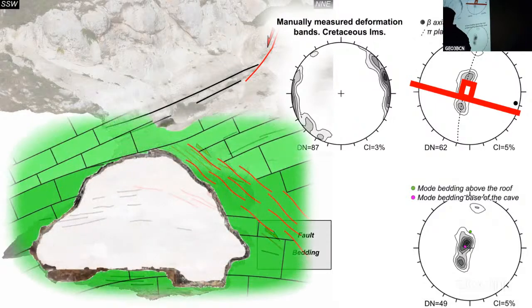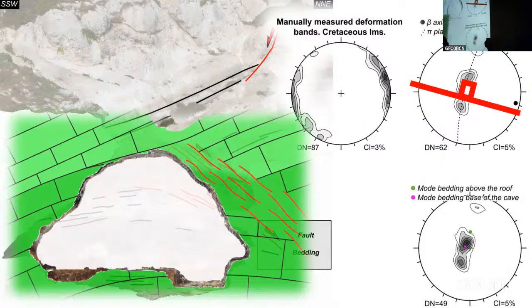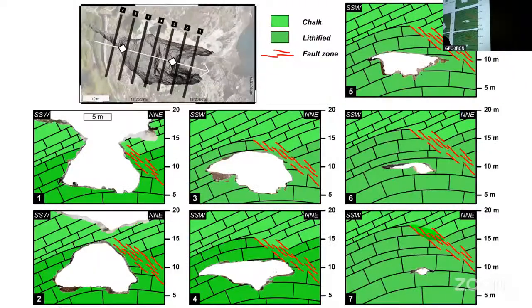And that's the geological cross-section. That material is a little bit lighter. Okay, that's the chalky high permeability material. That's the limit between the lithified and the chalky material. And that's an embryonic normal fault, which is characterized by discrete planes with no big evidence of shear.